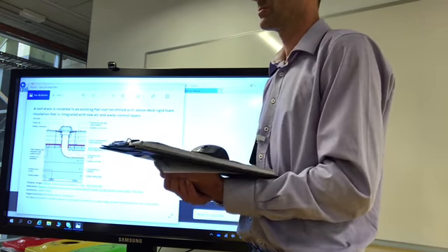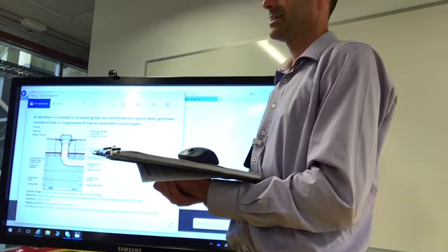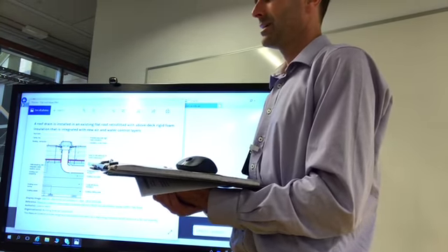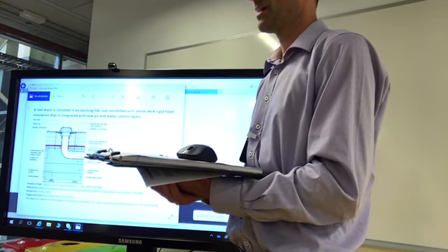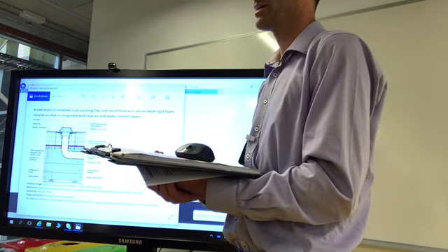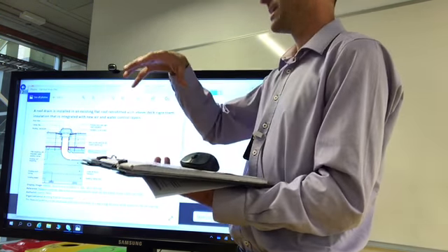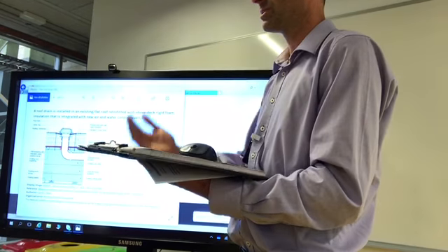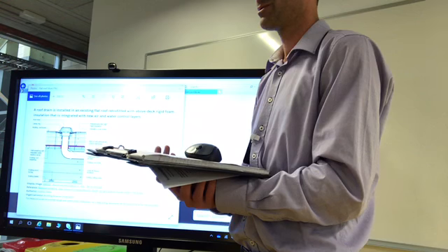Would that system be applicable if you were to put a deck over the top of it? Because essentially the deck will still let the water through, and that would still be the water system. Yeah, but of course, attaching the deck, that'd be the point at which I'd expect things to be leaking. Also, the supporting of a deck on top of a membrane, even if you're not piercing through the membrane, I imagine there'd be issues in terms of any movement and wear that happens as a result of that as well.